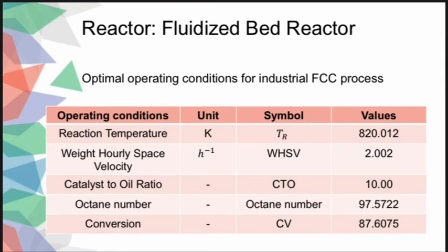So as we can see from the slides, the operating conditions include a reaction temperature of 820.0012 Kelvin, weight hourly space velocity of 2, catalyst to oil ratio of 10, octane number of 97, and also a conversion of 87.6075%.